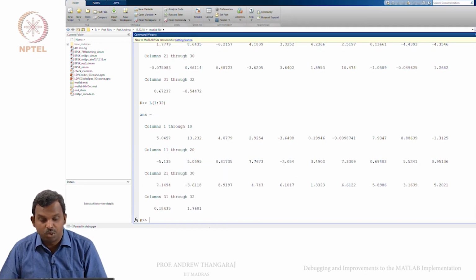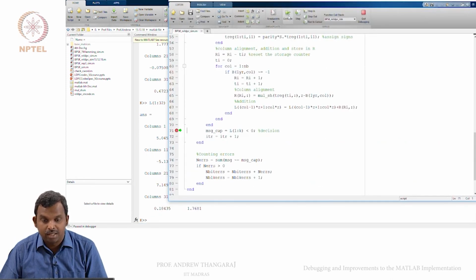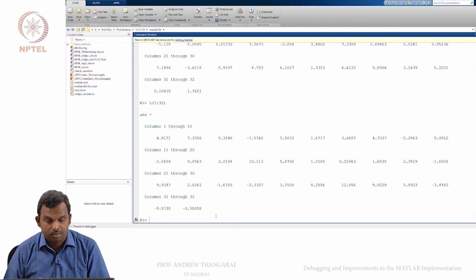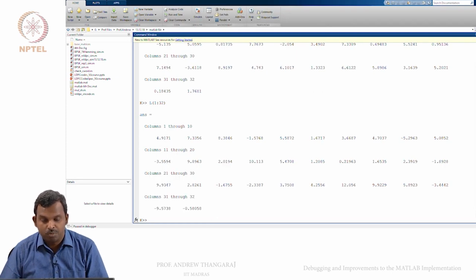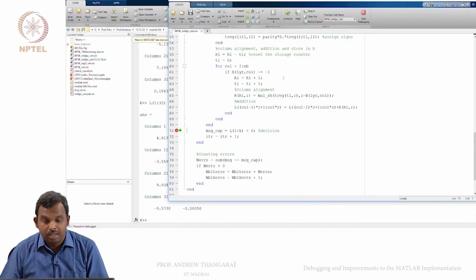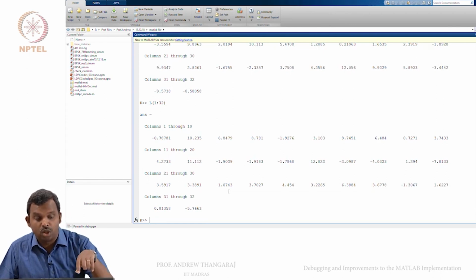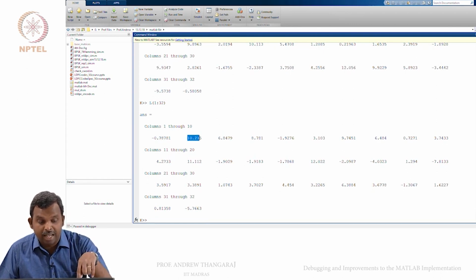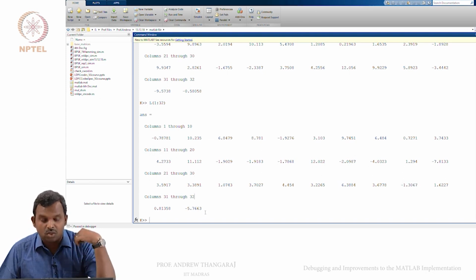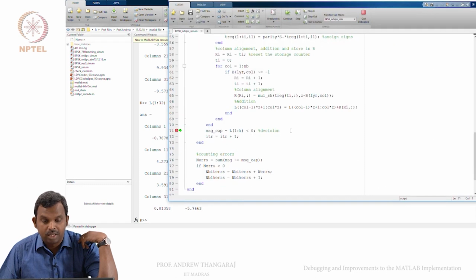Maybe this is some good news. I'm not sure. Let's continue again. Okay. So errors can happen. It can happen that there are some errors that you don't correct, and you'll go through and see how it is. But this is an instructive way of seeing what's going on. So, you see, some of the bits are becoming very reliable, right, 10 and all that, but some bits are still lying out there, minus. These are all errors. Okay. Anything negative is an error. Okay. So, 0 dB Eb over N naught for this code, maybe at this block length, is not very good. Let's see that.